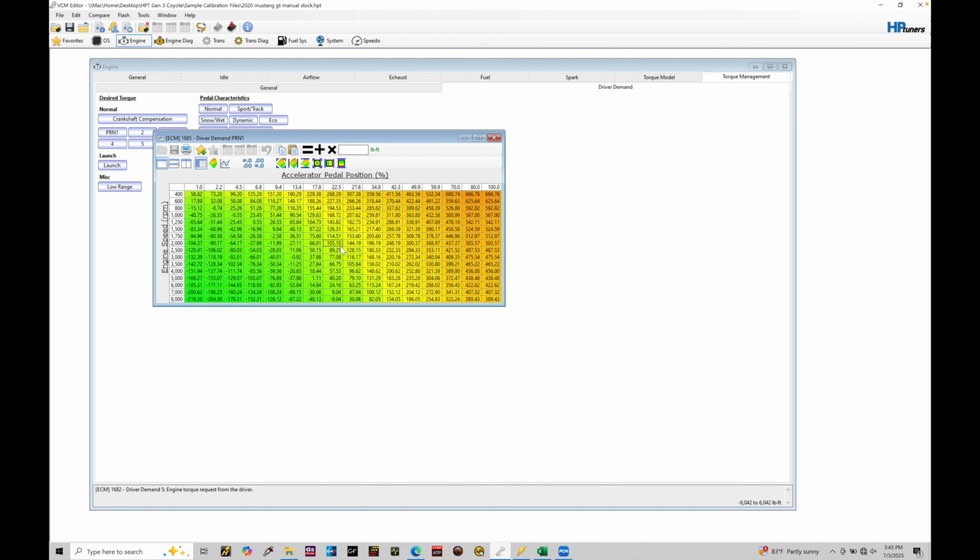This is the beginning of our torque-controlled system. Now, what's important to understand about this is the net torque that we want to request from our engine. Net torque is going to be the engine torque minus any frictional losses or pumping losses that can happen with the engine. So this is what we actually want to be able to deliver versus our throttle pedal.